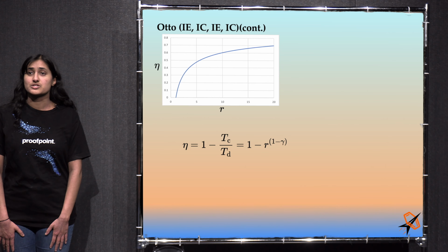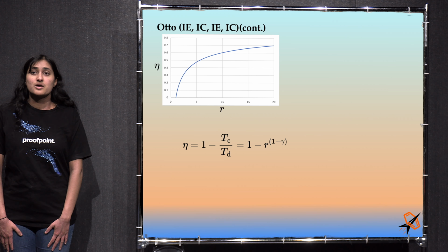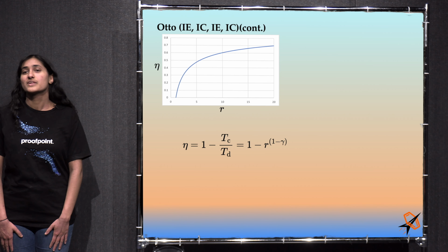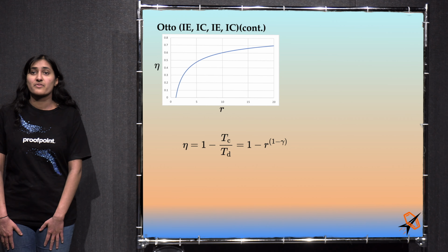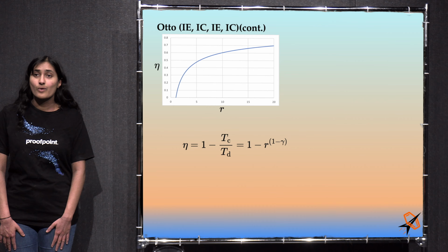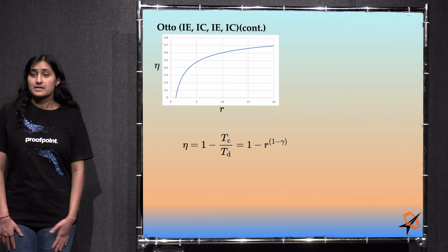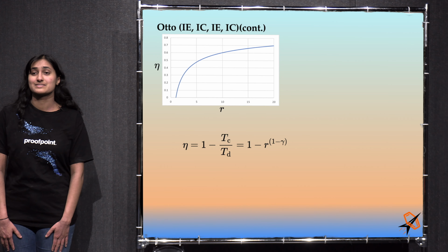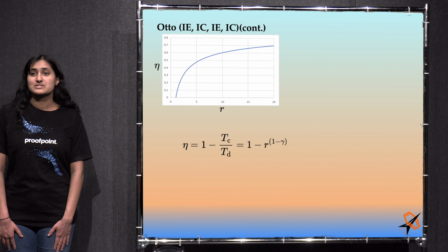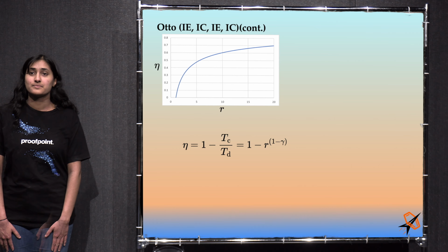The higher the compression ratio, the higher the octane rating of the fuel has to be to prevent pre-ignition or knocking. Prior to the 1970s, they used to add tetraethyl lead to increase the octane rating. In the 1970s, tetraethyl lead was outlawed, except for aviation fuel, to prevent the poisoning of the catalytic converters that were required to meet the new air pollution standards. The side effect is that humans also suffer much less lead poisoning now. Sometimes the unintended side effects are good. Many further details on the Otto cycle are available on Wikipedia.